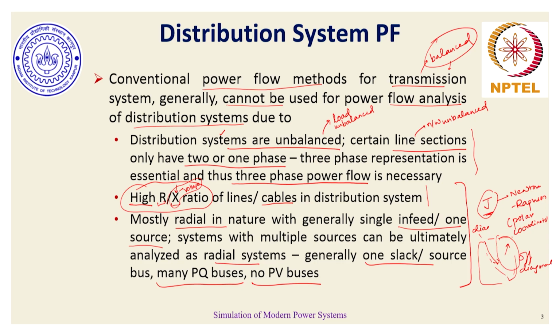The other reasoning one can also understand is that in the fast decoupled method, we understood that real power and voltage phase angle have strong coupling, and reactive power and voltage magnitude have strong coupling.